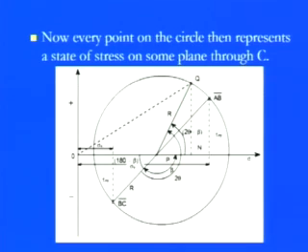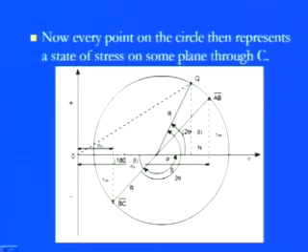So now what we have is sigma theta and tau theta. What is sigma theta? Sigma theta is sigma x plus sigma y by 2. So sigma x, you can straightaway plot that this is my sigma x. So sigma x is nothing but this BC. If you plot these, this is my sigma x, and if you drop this line, projecting this line on the x axis, because sigma x and sigma y are nothing but the interception of these points, this BC bar or AB bar, on the x axis.